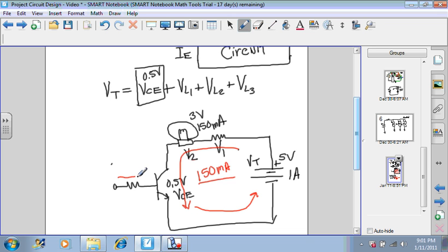Remember, over here, this is being taken care of. We have pushed the transistor into the saturation region, which means the base no longer controls the current directly, and we can just push as much current as we need through the collector, because now the transistor has collapsed, and now the current is being controlled by the circuit over here. As long as we do not exceed the maximum collector current that's allowed by the transistor, then we can operate a wide variety of load circuits.